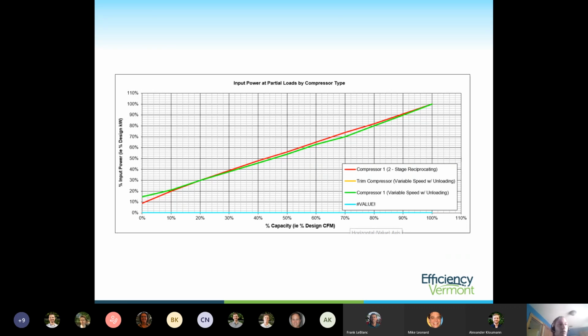So when tolerances of manufacturing became really good and got better as we got smaller on systems, the rotary screw compressors have started to really take over the reciprocating compressors in the larger horsepower, because they're not anywhere near as loud, and they don't cause so much vibration. So they're a lot easier to put into a plant that needs a high horsepower compressor.